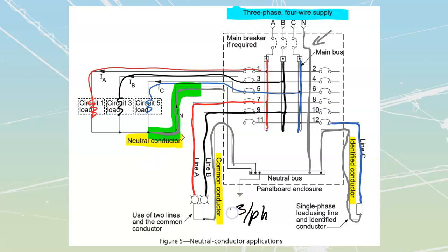Let's take a look as well at a couple of our other conductors that we have up over here. We're going to label off some of these. This conductor over here right now, from this load all the way up to the point where it makes connection to that, is only carrying back current from a single line. Therefore, we would call that one unidentified. I'm just going to put a U over there. That would be an unidentified conductor.